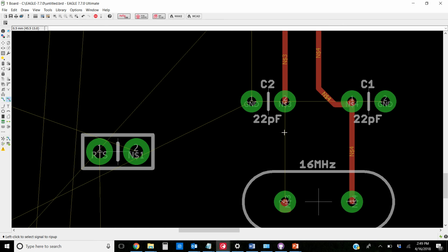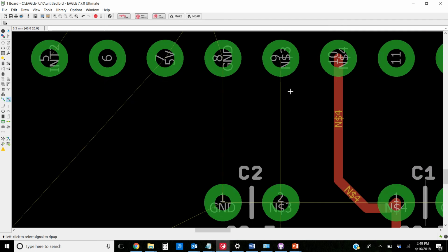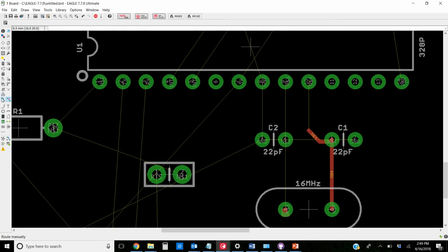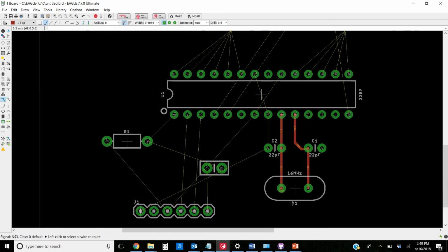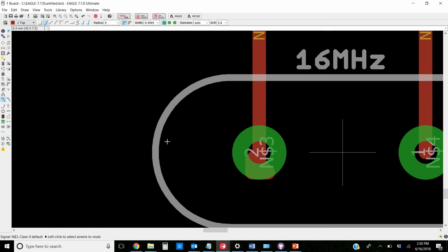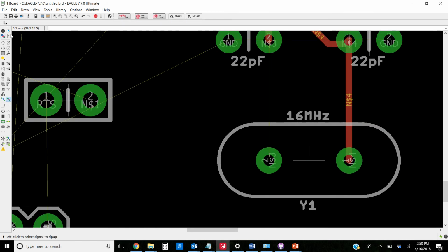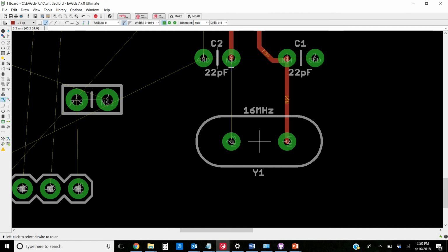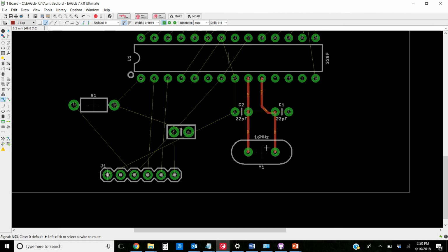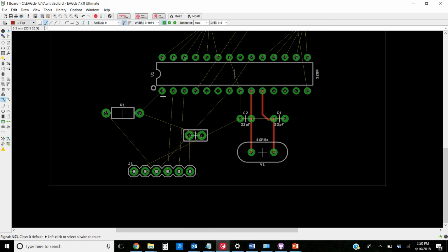And if I click on that line multiple times, I can get the whole thing to go away. So let's go back to route and put this all back together. Okay. And you can actually see, if you look close, there's a little bit of a goof up in there, routed around, so we'll just rip that up, reroute that, make that a little cleaner. Okay. Now let's start putting in the resistor pull-up line for reset.